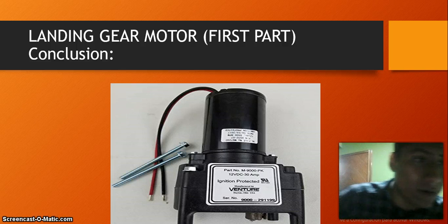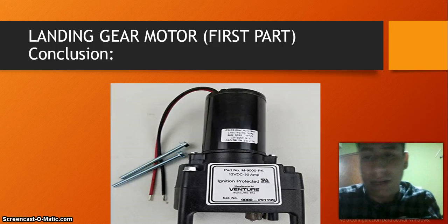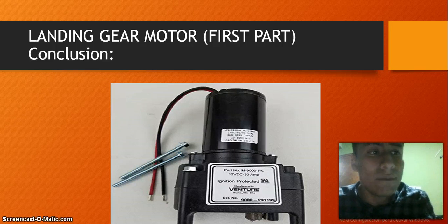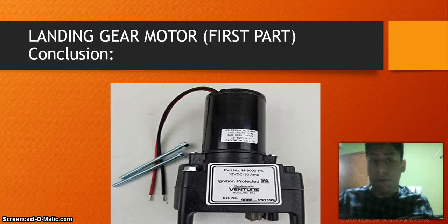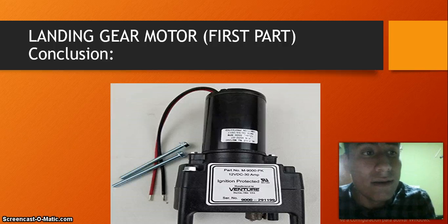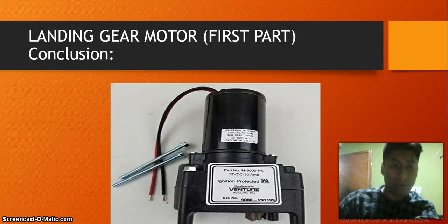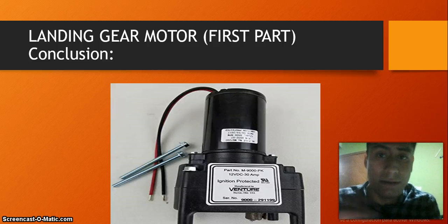The retraction motor operates the retraction transmission, which pushes the torque arms forward, which pulls the main landing gear cables and pushes the nose gear retraction tube forward, retracting the landing gear. When the gear is fully retracted, the gear up limit switch stops the motor, and the amber gear up indicator light on the instrument panel lights up.